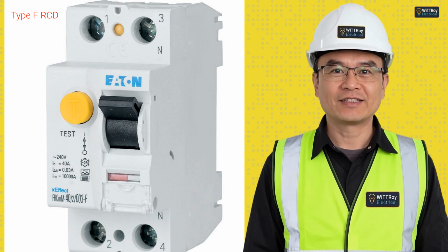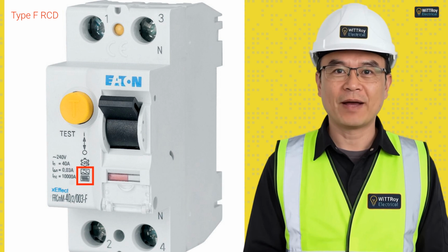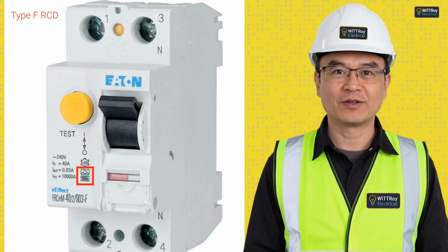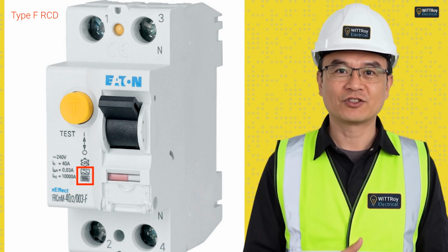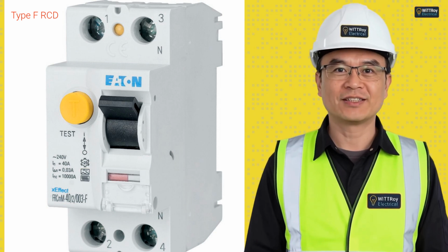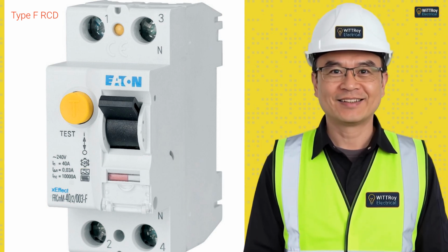Let's look at this device. The symbols show it is a type F RCD. Type F includes type A operation, but it is also suitable for high-frequency leakage currents. It is often used with equipment such as frequency converters, electronic ballasts, and some motor drive appliances. So this is a type F 30 milliamp 40 amp RCD.